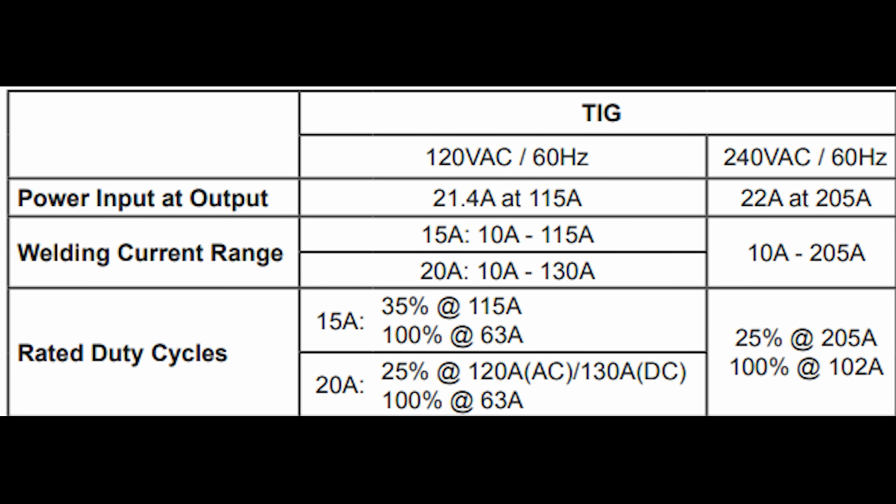So if you're welding anything over 3.2 millimeter thick or 1/8 inch aluminum, and you're doing things like fillet welds, you're going to need all of that amperage, all 200 amps of it, at least at the start of the weld. And if you're welding anything thicker than that 1/8 inch, then you're definitely going to be full pedal, and you're probably going to end up hitting the duty cycle of the machine pretty quickly.